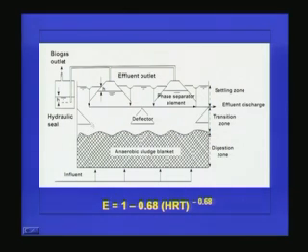So we are providing a specific system here, including this deflector beam and this cone arrangement. This is known as the gas liquid solid separator, and we have seen in detail how to design it. The basic objective of this GLSS is to separate the solid, liquid and gas phases, so that all the biomass is retained in the digester zone, the biogas is collected here and can be used for other purposes, and we get completely treated clear effluent here, which can be discharged without any problem. This will meet the effluent standards. So we have discussed in detail the digestion zone design, settling zone design and GLSS design.